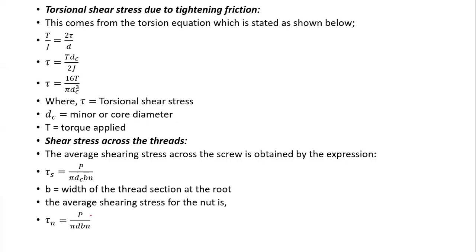That's how you may find that. It's the same thing we're seeing here, except we use a different value for D, because this is now for the nut, and that one was for the screw. For the nut, we're using the core diameter. For the screw, we're using the nominal, the major.